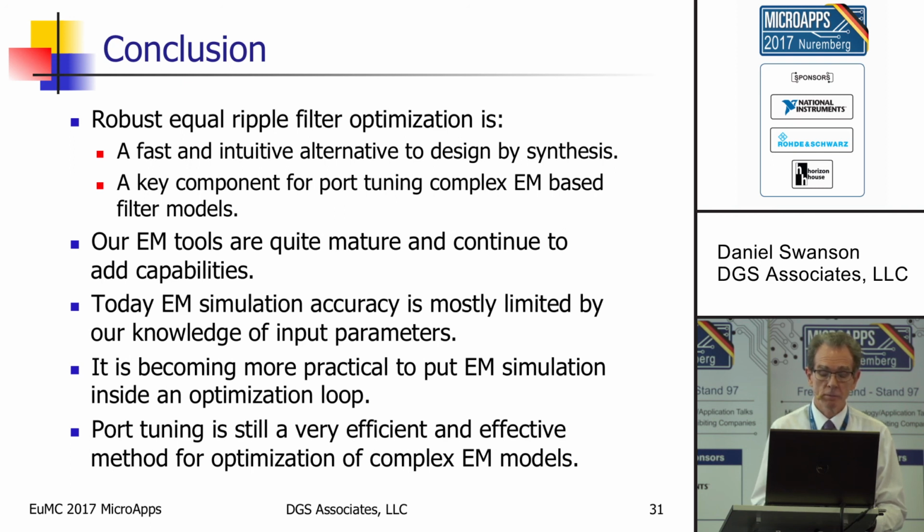And we may see more and more EM simulation directly driven by the optimizer. We're not going to be able to do a lot of this yet, but again, I think this will evolve. And the port tuning is still, I think, probably the most efficient and the most effective method for optimizing a complex EM model.